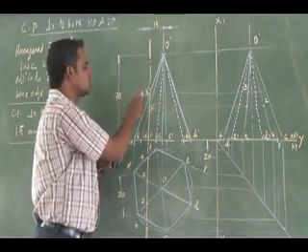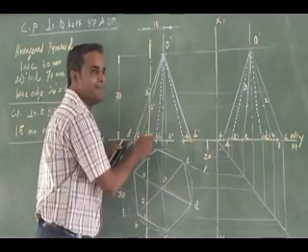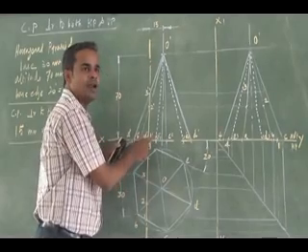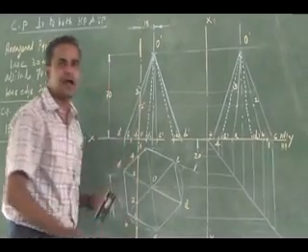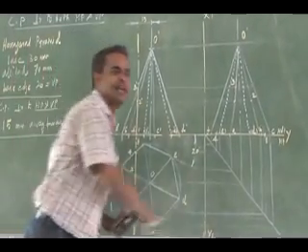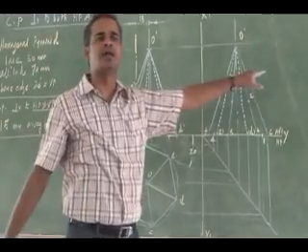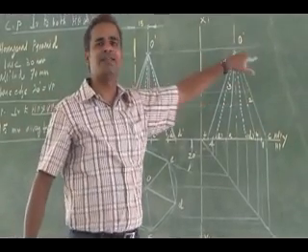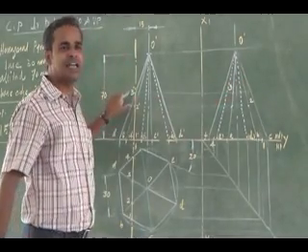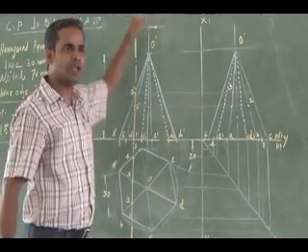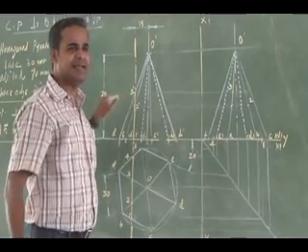3 is another visible slant edge, AO. Then come back in the same manner to mark the hidden base edge, 4. Right. So totally I have marked 4 cutting points. So these cutting points 2 and 3 fall on the slant edge.